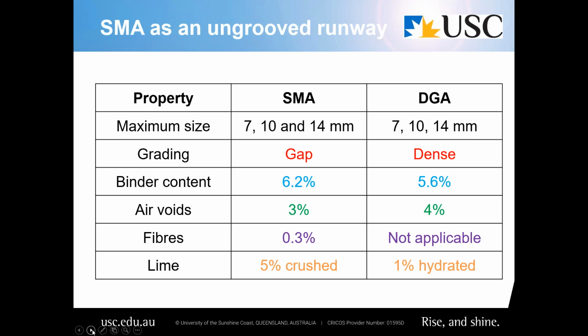And we use the crushed limestone because the percentage of lime is so high, about 5% versus 1%. If we put 5% of hydrated lime into any bituminous or asphalt type mix, we'd make a very stiff and brittle mix. So we use a different kind of lime, crushed lime, instead of that fine powdery lime that we might be used to.